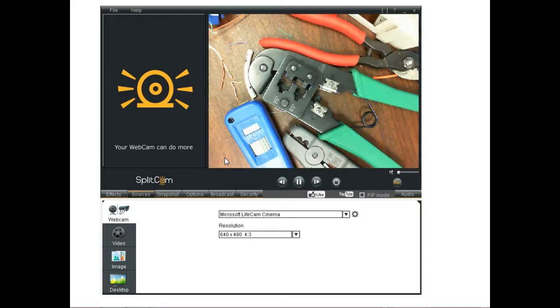But then you got to do what? You got to double check that color code, right? Before you crimp it, you got to go double check that thing, because once you crimp it, then if you do it wrong, Rich is going to take off some points, and then what are you going to do? You're going to cut it off and redo it, right?